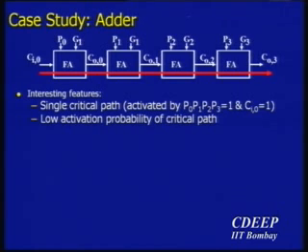So if I look at a ripple carry adder, it's a simple-minded example showing that, hey, if I have a 16-bit ripple carry adder, let's say, it's possible for me to look at bit number 8, just as an example. It doesn't have to be 8. If I look at bit number 8, and the input to that bit number 8 is 0, 0, I know there is no carry propagation, right?